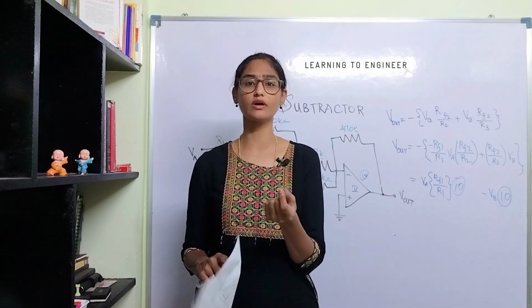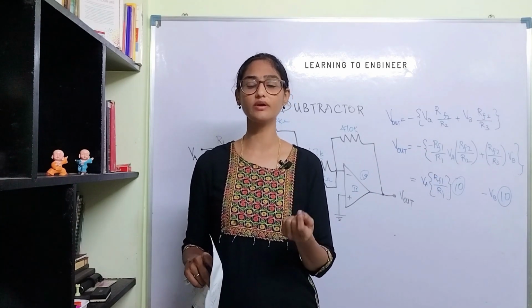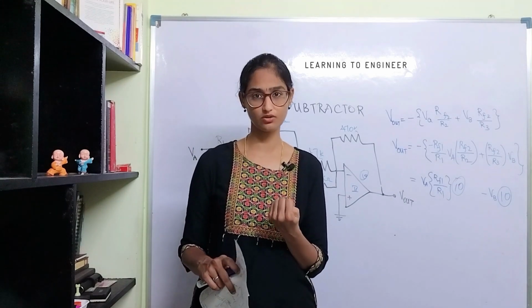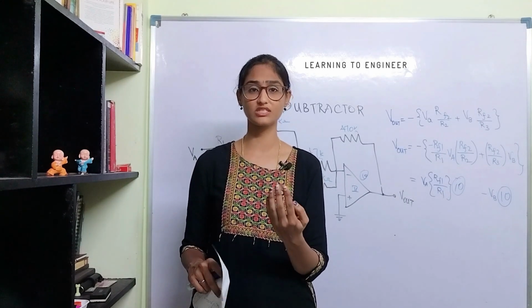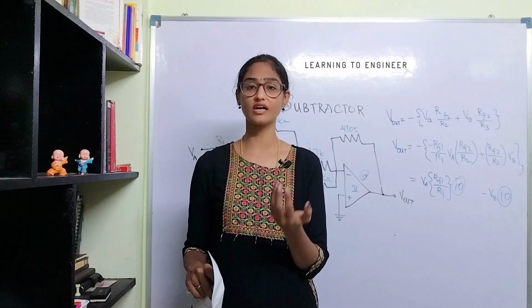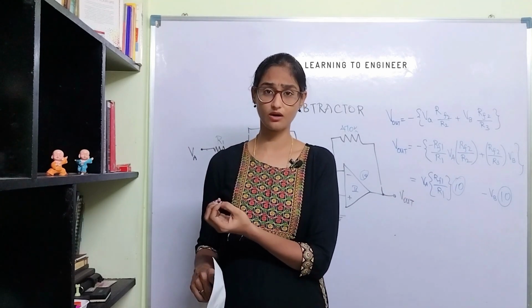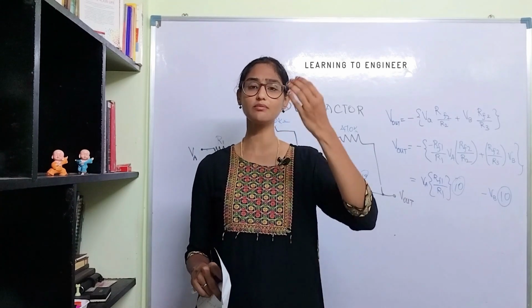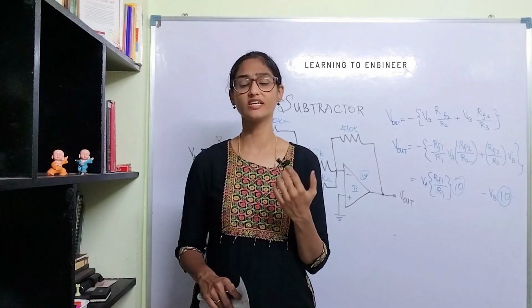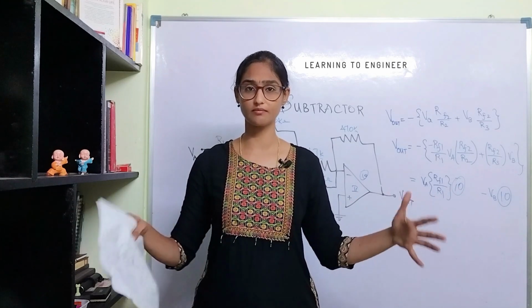If you are sending a few microvolts, the circuit will not be able to accept that sensor's output to display it as a digital reading. Even to sense the sensor's output, it needs to be in a measurable amount of threshold. So we definitely need gain multiplying amplifiers.